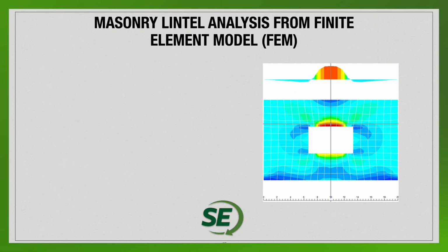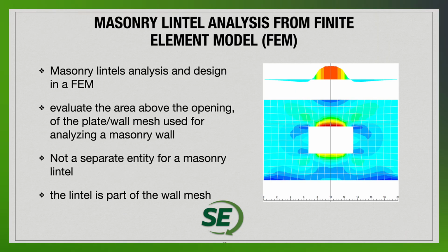So finite element analysis does give us a nice ability to look at the forces in the lintel and see what some of the different forces in the adjacent elements would be for the design as well. So it's not a separate entity. The masonry lintel is really going to be part of the overall wall mesh, and certainly looking at the forces, I think it helps us have a better understanding for lintel design.